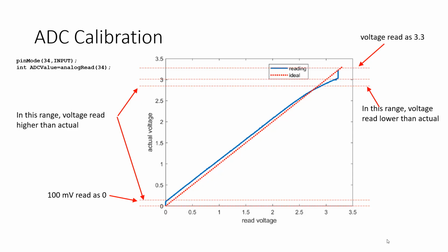If it sets the power supply to a specific voltage, then it knows what the input voltage is on the ADC, and then it reads the ADC and looks at the difference. It says, there's a difference between what I'm reading and what I know is there because I'm the master of the power supply. So then you can build up this calibration model, and create an automatic correction mechanism to correct the ADC.